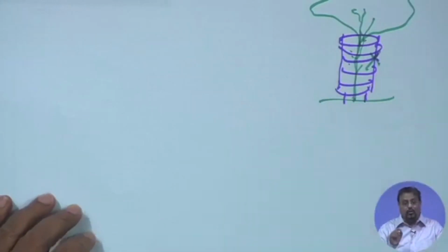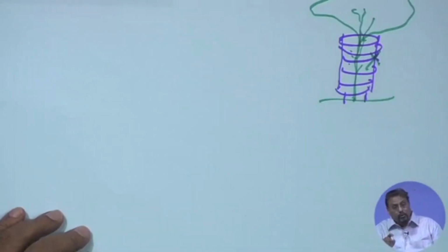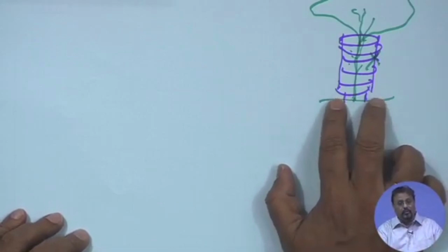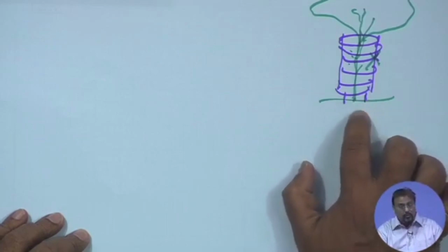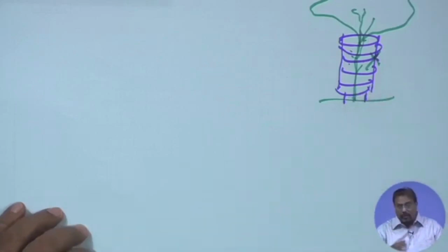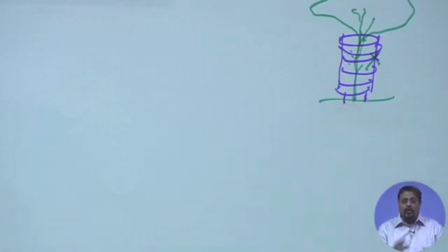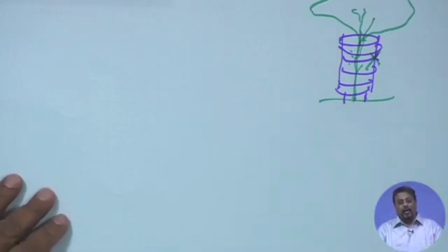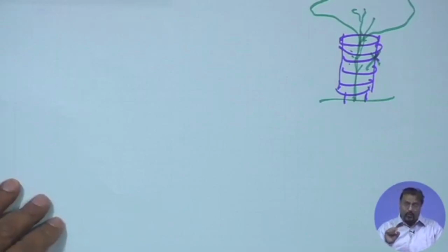So in your construction document, there should be provisions for these kinds of tree guards, and there would also be instructions on how long the tree guard should be there. After that, the tree guard is removed, because the contractor has to pay for the execution of this and charge you for it. Later, when you are removing it, it either gets recycled, which is the best possible way, or it is thrown away. Now, once the tree guard is removed, the tree is bare. It is now accessible to the cattle and vandals. If such things happen, how is the tree going to survive? So you have to really specify to that much detail.